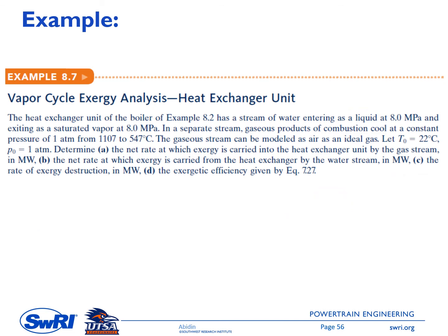Let's take a look at an example to give us more understanding of the exergy analysis of the Rankine cycle. First is to analyze the exergy within the heat exchanger. So this heat exchanger is the boiler itself. Looking back at example 8.2, this heat exchanger has a stream of water entering at 8 megapascal, and then exiting the boiler as a saturated vapor at 8 megapascal as well.